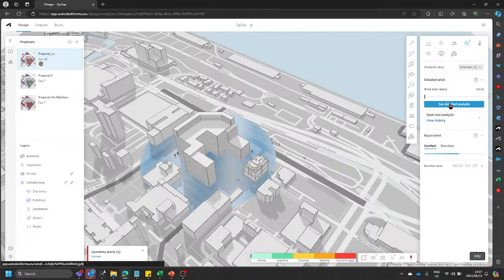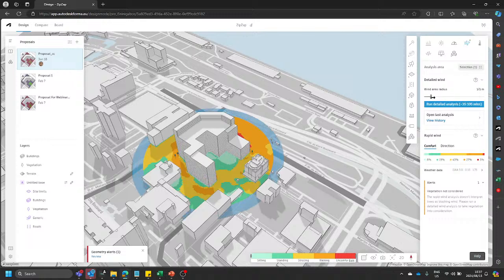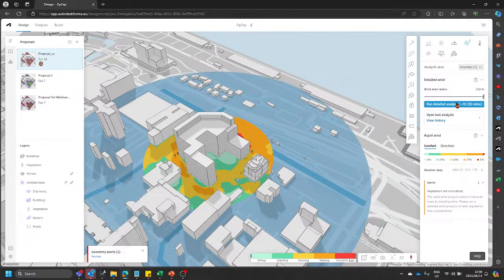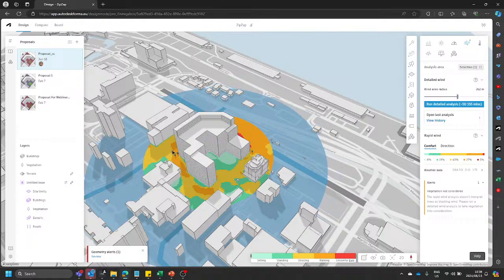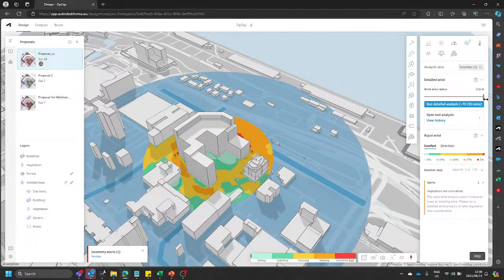And if you look at the detailed analysis results, you can see if you wanted to do a new analysis, then the bigger you choose your radius, then the longer the computer will take to run through it. Right? So to do one wind analysis for a shape, this might take 155 minutes on the outside. If you decrease the radius of the wind, then it takes less time. So it's all time dependent, right?